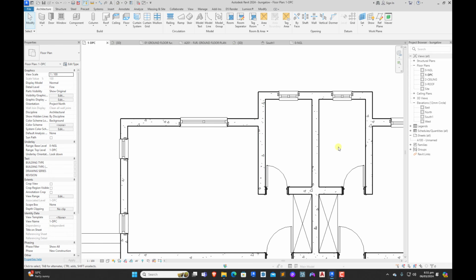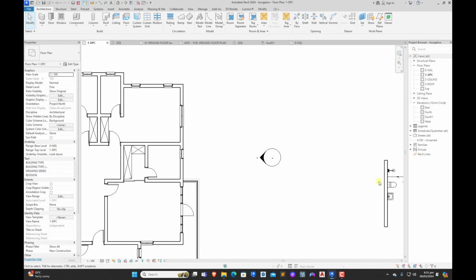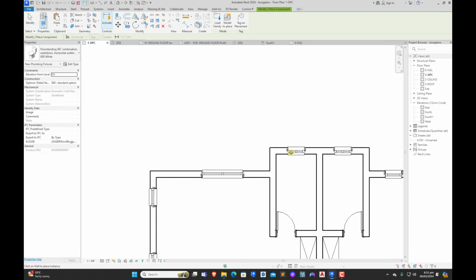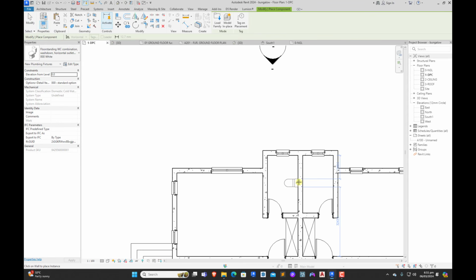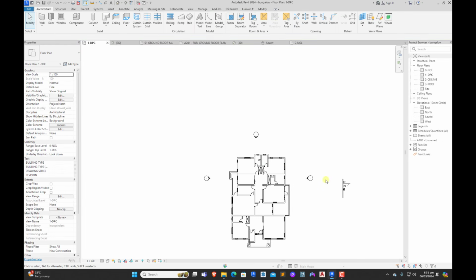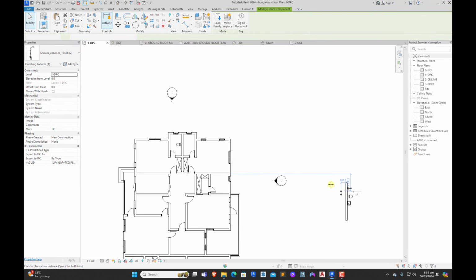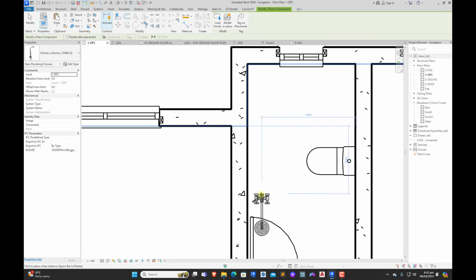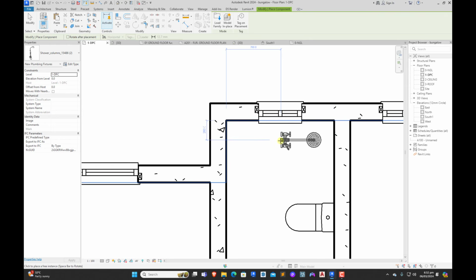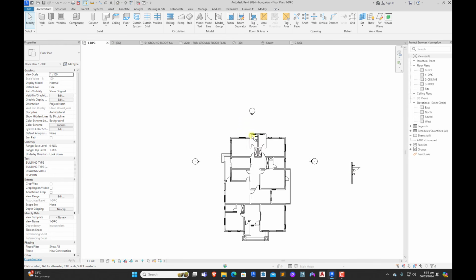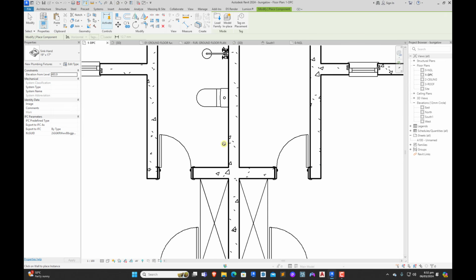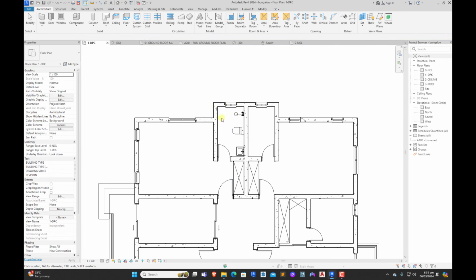Okay, so we're going to be furnishing this toilet now. I already have my furniture here, so I'm just going to click on this toilet. Click on CS to create similar. Then I come and place it right here. You do the same thing for this shower head. CS to create similar. Then you click on your spacebar to rotate the components. You click it here. Then you do the same thing for this. CS to create similar. You come here and you place it right here.